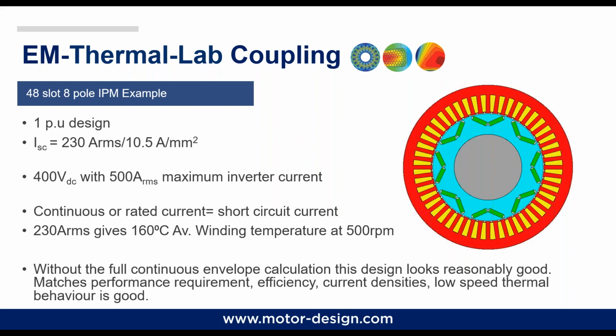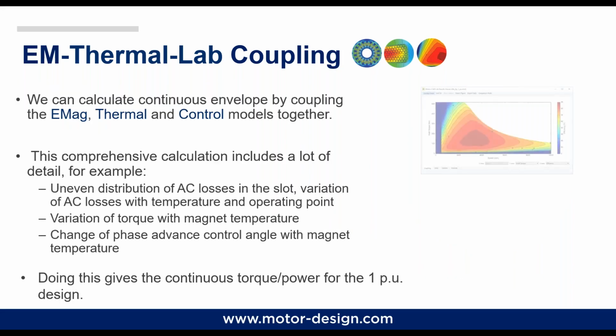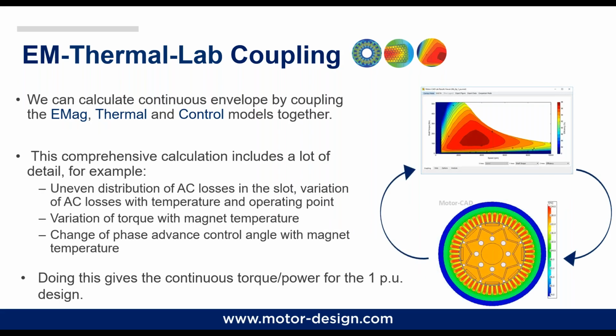So it matches the performance requirements, the current density is reasonable, and the low speed thermal behavior of the machine is good. So I could say this design is good enough. But when we actually do this with MotorCAD, what we do is not just to have a look at